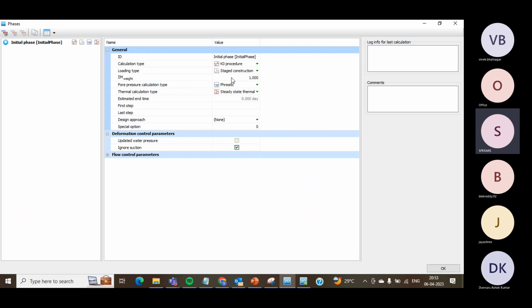So this is where, when your boss asks you, can you do me a favor and vary the densities of your material and confirm the behavior? If he says 10 different densities, are you going to add all these 10 different densities to your material properties, creating 10 different material properties, and each time change your material properties? No, it's as simple as that. The M weight, you can change these values.